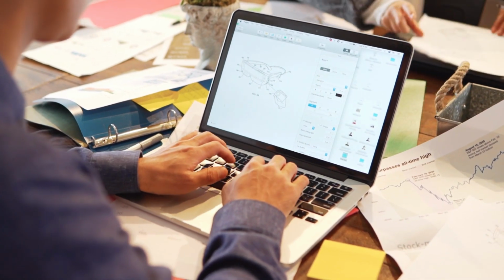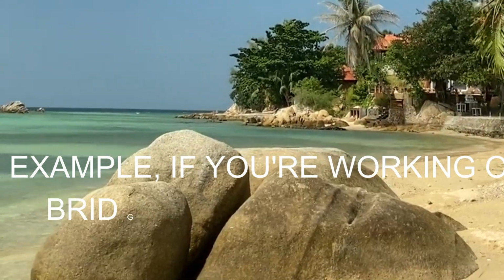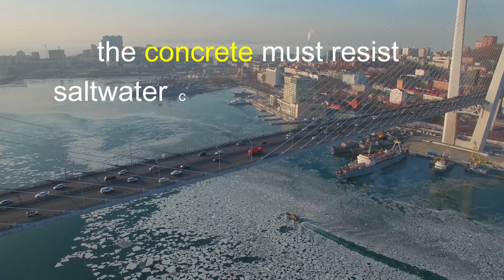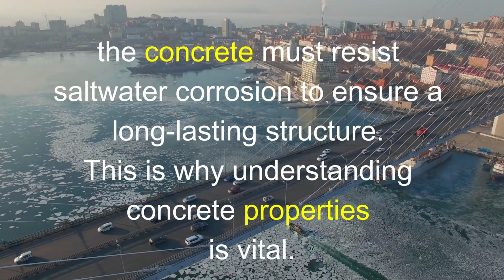Let's move on to the next critical concept. Question 5. What are the key properties of good quality concrete? Good quality concrete should have adequate compressive strength, durability, workability, and resistance to weathering and chemical attacks. These properties ensure that the concrete can handle loads and resist environmental factors over time. In areas with extreme weather conditions, like coastal regions or areas with freeze-thaw cycles, good concrete durability is key. For example, if you're working on a bridge in a coastal city, the concrete must resist saltwater corrosion to ensure a long-lasting structure. This is why understanding concrete properties is vital.